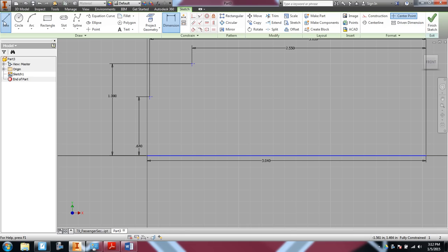Okay. Next, we're going to use the line tool to draw the arcs, and this will get those tangents created for us. So if I click and hold, I can start drawing an arc with the line tool. And then you want to make sure that you drop it on that endpoint, which when you're on the endpoint, notice the endpoint turns green. So again, that is click and hold for the line tool to become an arc. And then that'll make it continuous, and you also see when I start doing that, I get the little tangent symbol that also pops up. So that creates all those tangents.